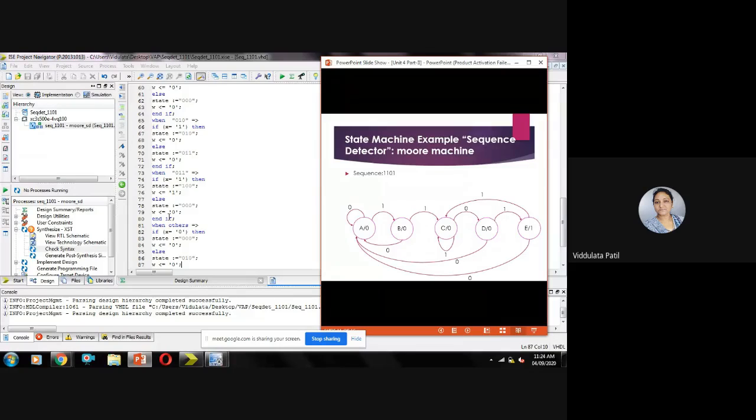Okay, now here actually we used a 3-bit variable for the state. So we will have certain other next states, that is 1 0 0, then 1 0 1, and so on, but we are interested in 1 0 1 only. So for when other cases for state will be there, we are going to keep x equal to 0.